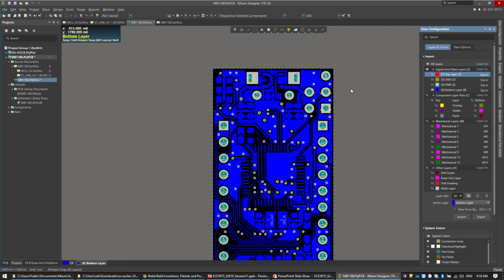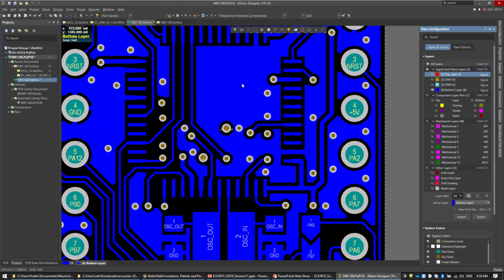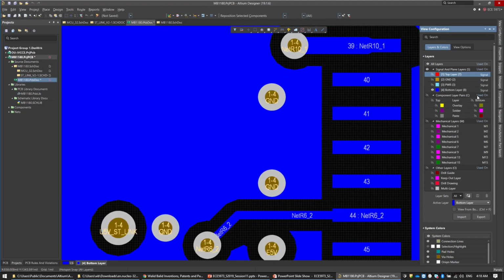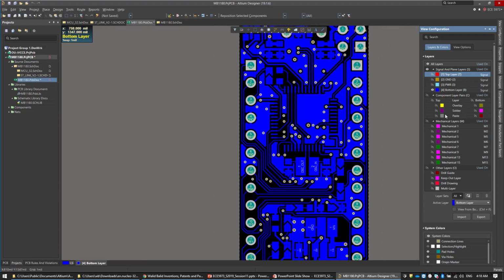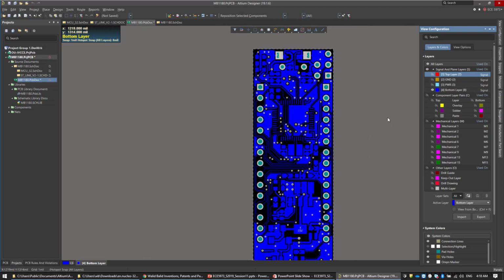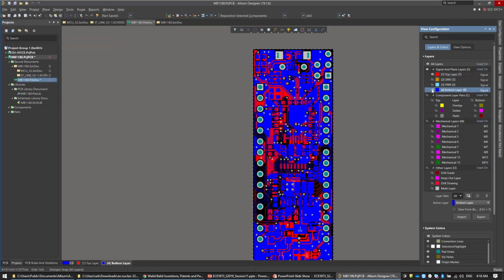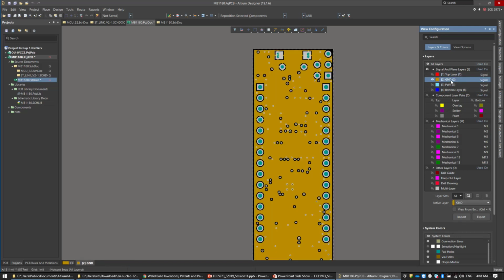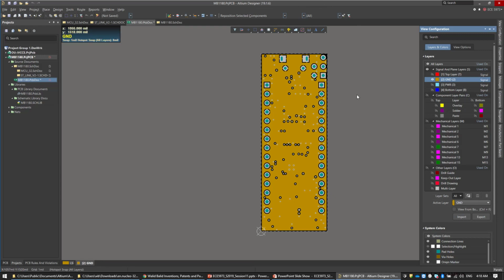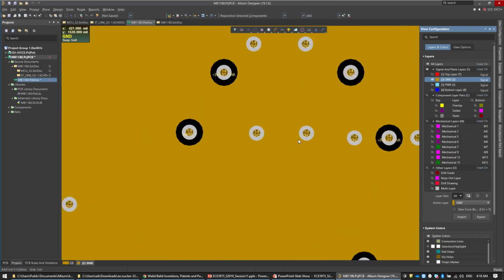It's everywhere on the top layer. And if we look at the other layer, you have the bottom. Also, you have a component, and also you have a ground pour in here. So they have a component and a ground pour, and this is very good practice, to have ground pour around the signals. And let's take a look now at the inner layer, and this one is called the ground, as you can see, and everything on this layer is just the ground.